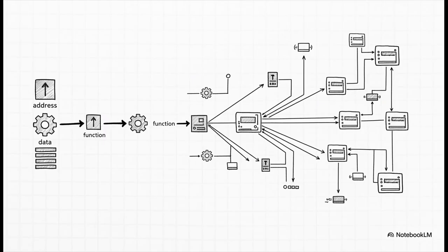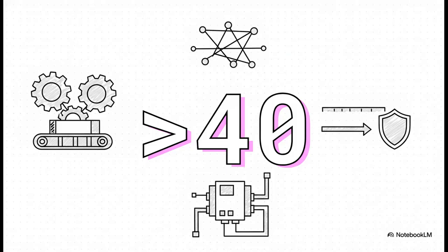And that's the crucial point, really. The elegant simplicity of Modbus is its greatest strength. By just combining these few basic parts, address, function, data, you can build these incredibly complex and super reliable control systems. And get this, this simple, robust system has been around for over 40 years. It was originally developed way back in 1979 for these things called programmable logic controllers, or PLCs, and it has outlasted countless other technologies that have come and gone.